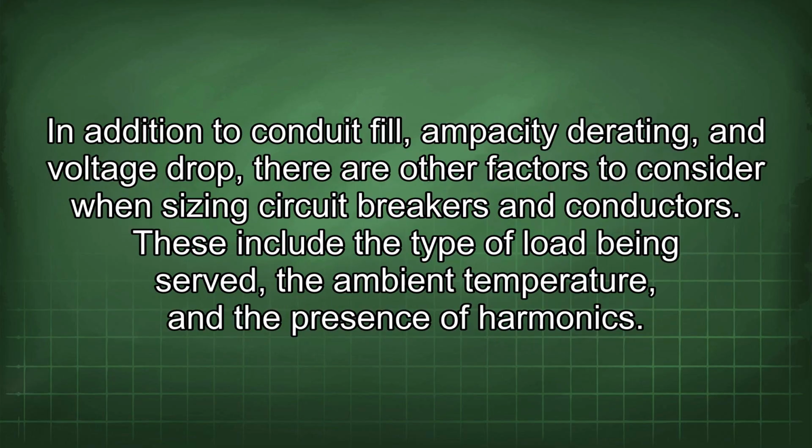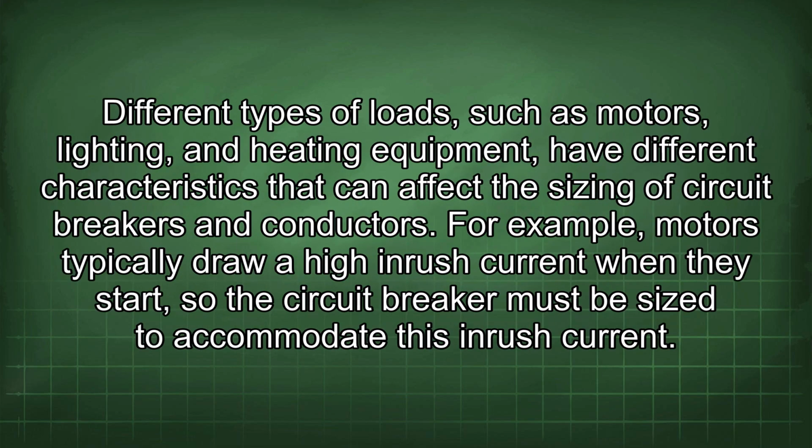the circuit. In addition to conduit fill, ampacity derating, and voltage drop, there are other factors to consider when sizing circuit breakers and conductors. These include the type of load being served, the ambient temperature, and the presence of harmonics. Different types of loads, such as motors, lighting, and heating equipment, have different characteristics that can affect the sizing of circuit breakers and conductors. For example, motors typically draw a high inrush current when they start, so the circuit breaker must be sized to accommodate this inrush current.